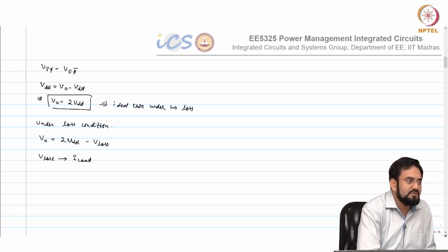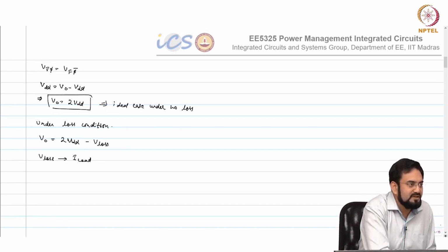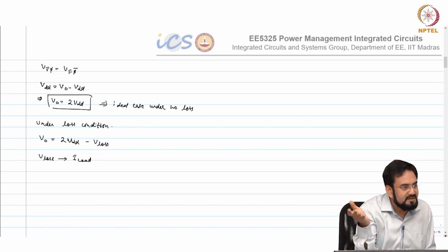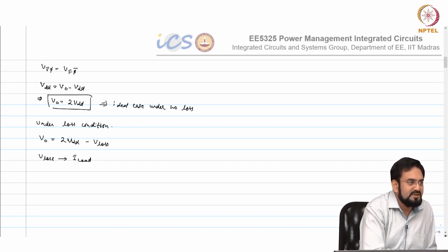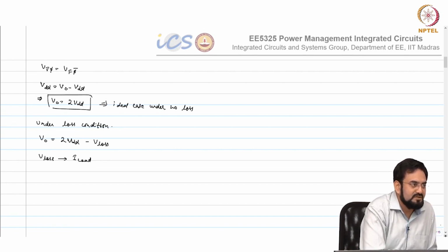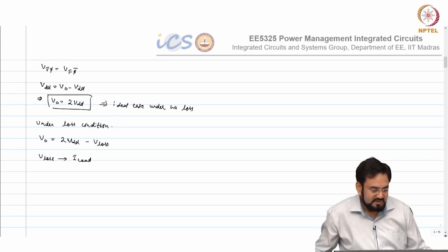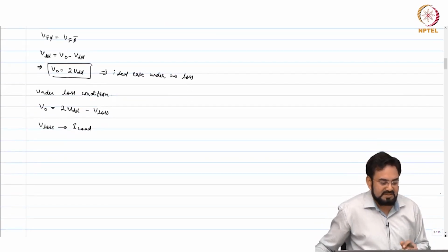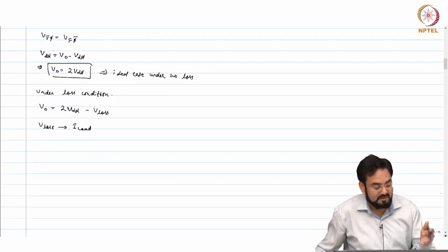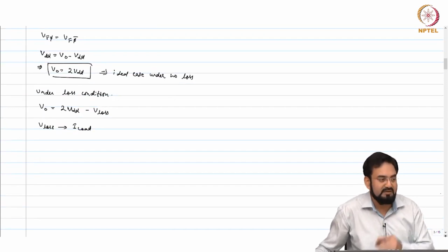So what you do is divide by 2 from the charge pump. So 10 volt becomes 5 volt, and now from there with a roughly 20% duty cycle you can get 1 volt output. Okay. So in open loop these are the applications, but sometimes we use these in the closed loop also, and we can regulate the output.